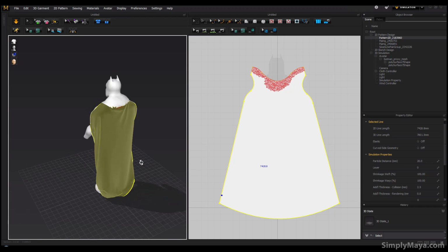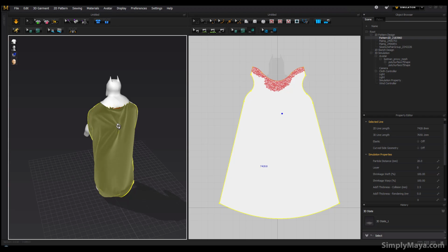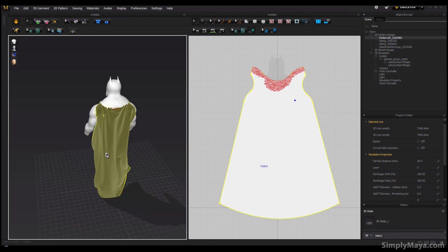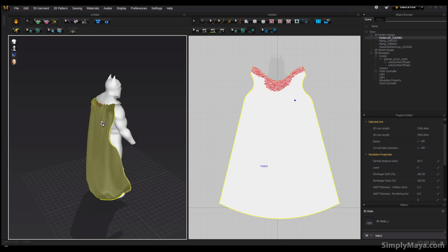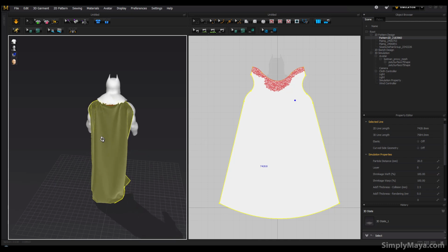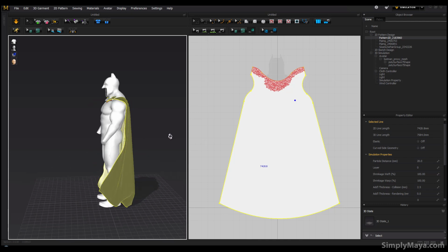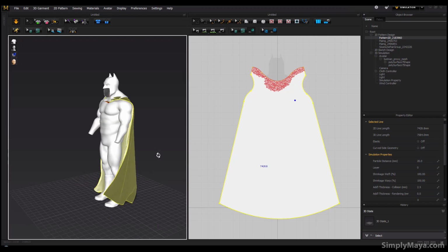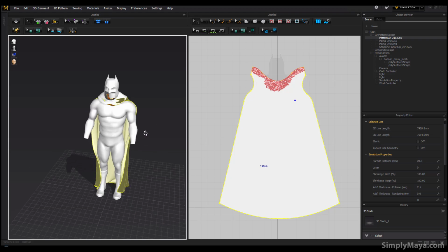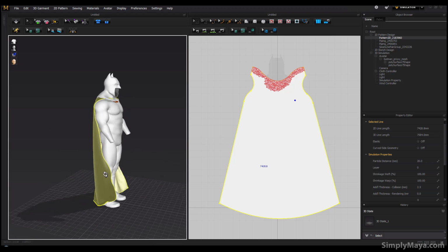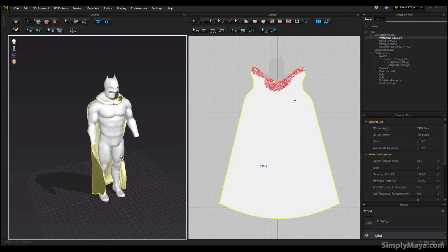So I'm going to let this settle down and maybe pull it about so it has slightly better bunching. There we go. And we're set on leather now, so you're going to get less of the really fine cloak type things and more of the big folds that you'd see in leather, and less of the tiny wrinkles that you might get in, say, a silky material. Okay, but that's enough for now. Now you can go ahead and get whatever look you want. I think it's kind of cool that it's wrapping around the feet, and obviously if that's settled down it will fall down flat, but this is enough for the next bit.